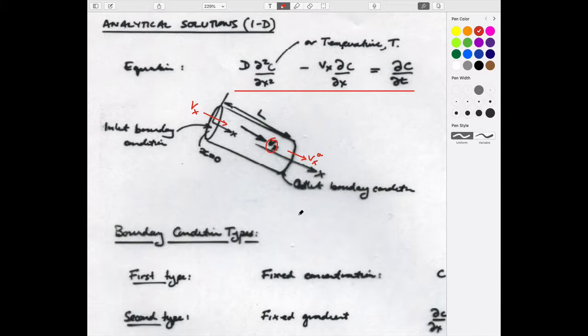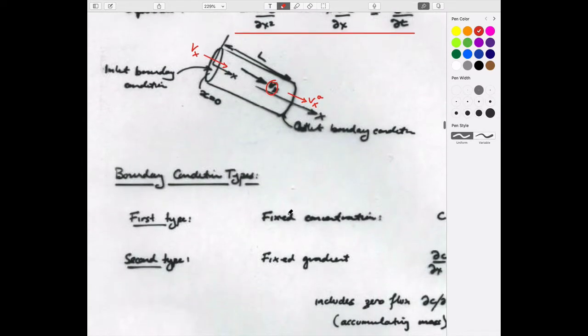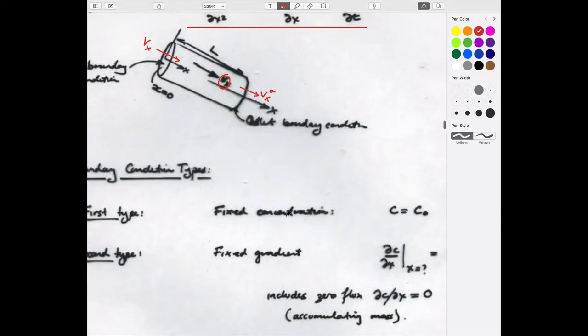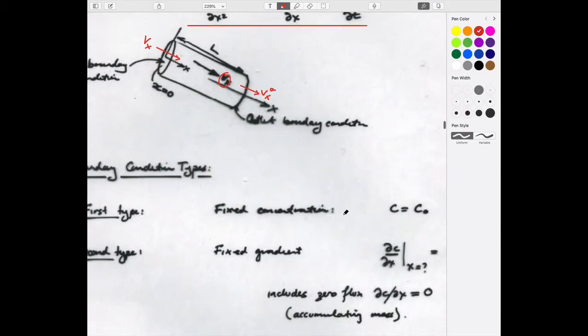It is the advection velocity. And we can imagine some different boundary conditions that we could apply. The most interesting to us, and the one that we'll use solely, even though they talk about different ones in Fetter's book, is a constant concentration.